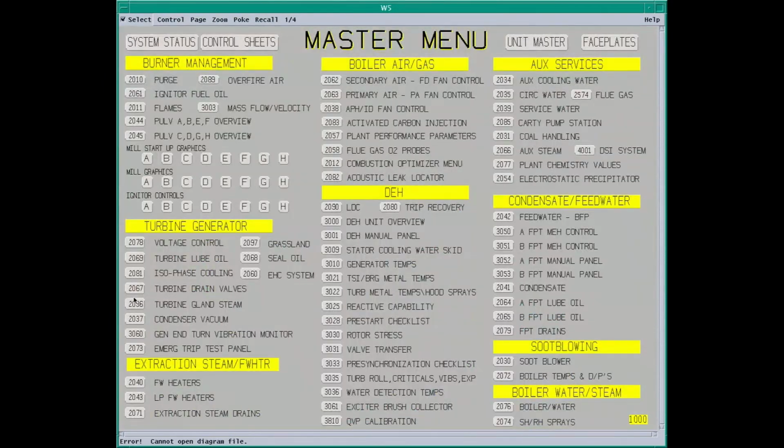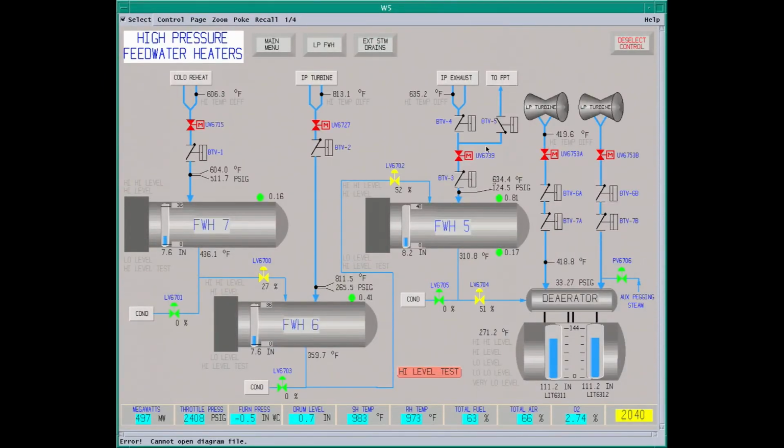The deaerator uses low pressure turbine exhaust. Extracted off stage is 16. You got your motor operated valves. These are for high level. These will close to prevent water induction into the steam turbine. 2 sets of BTVs, bleeder trip valves. There's a tremendous amount of energy in the deaerator, so you don't want this flashing to steam going back and driving your steam turbine to failure.